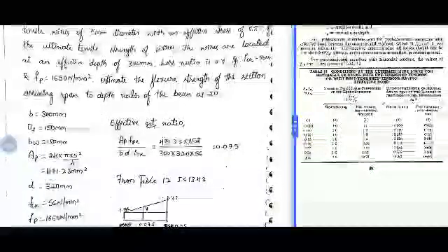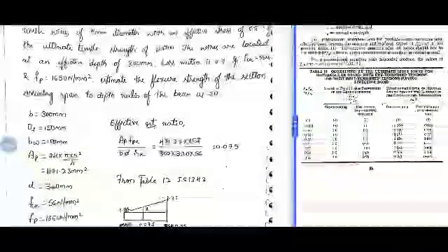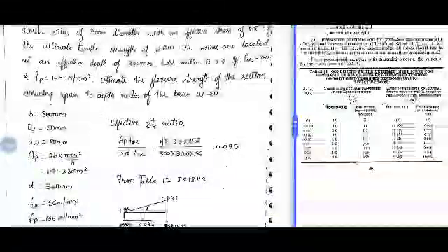So for the area of steel, it is given that the beam is pre-stressed by 24 high tensile wires of 5 mm diameter, so we need to find out the area. 24 into pi d square by 4, we will get 471.2 mm square. Then effective depth 320, FCK 56, FP 1650 Newton per mm square. So the first step again is the same, effective reinforcement ratio and L by D ratio. Since it is the unbonded case, but L by D ratio is directly given, it is 20. So directly you keep the value and calculate the effective reinforcement ratio.